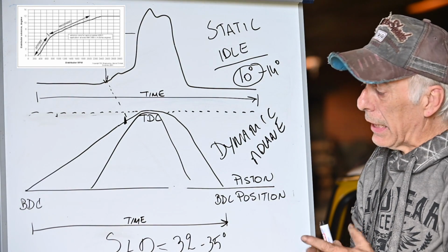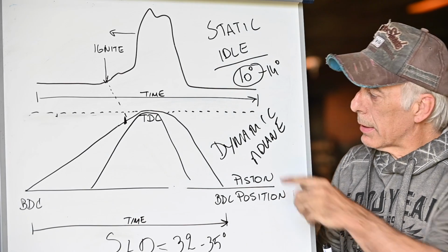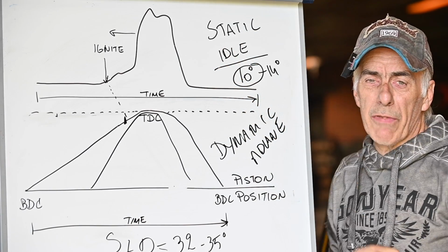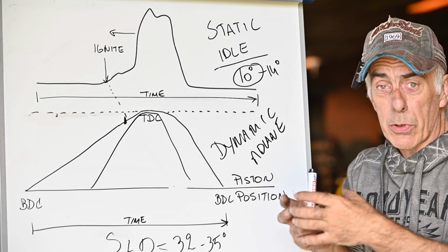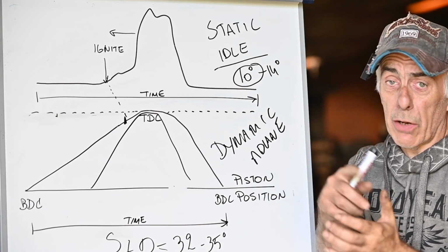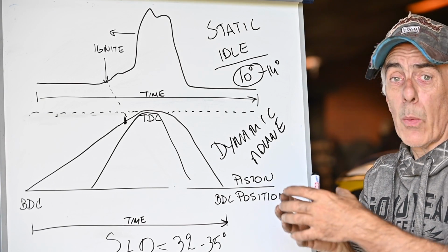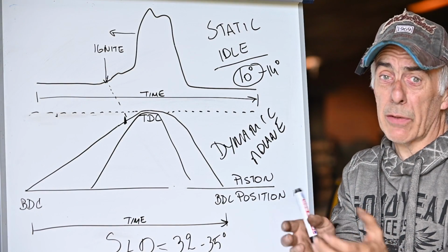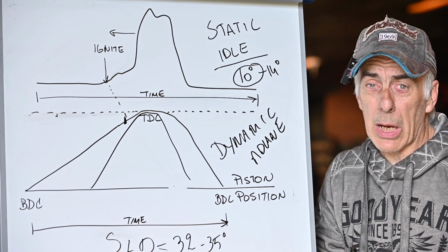So, having said that, now we need to look at how we're going to create this dynamic advance, because installing static advance is very simple. You just do it by rotating the distributor left or right, depending on the rotation of the rotor inside. By rotating the distributor while the engine is running on idle, you can actually adjust the advance. And of course, you're going to need a strobe light for that. We'll have a look in a few minutes at how you can do that.